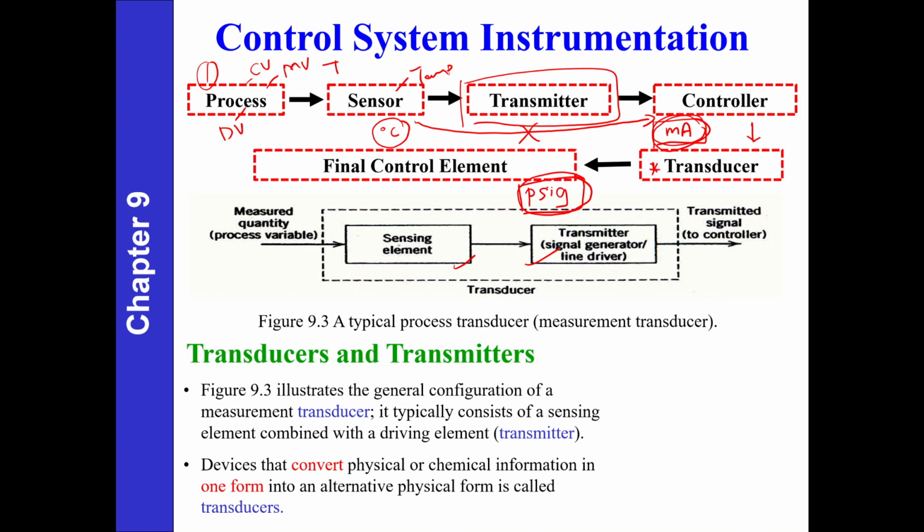But for me, it's easier to say that the function of a transmitter and a transducer is about the same, because it converts from one form to another form. For this transmitter, from degree C into milliampere. For this transducer, from milliampere into pneumatic.